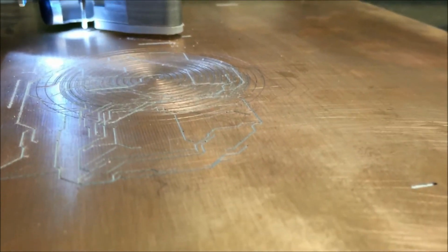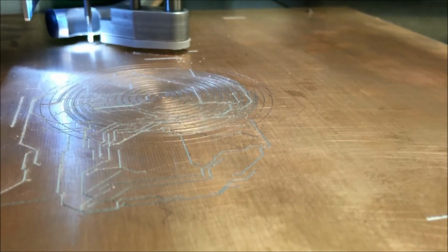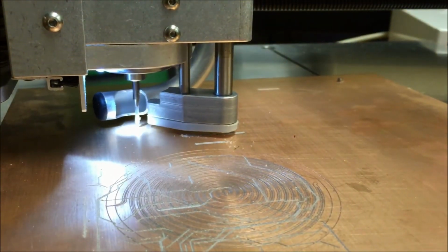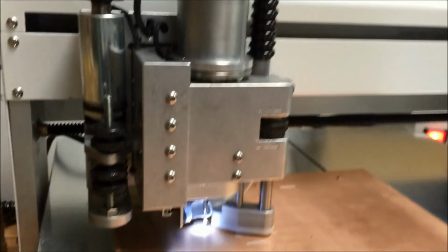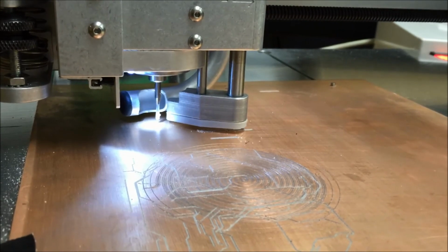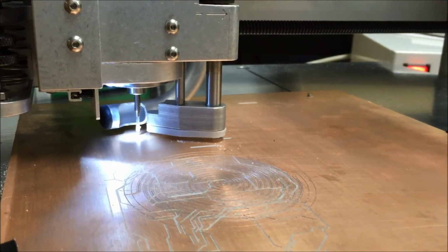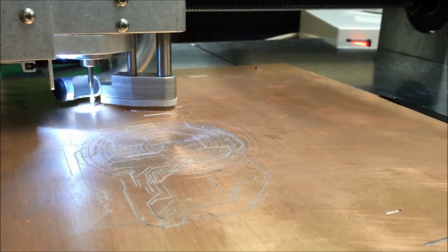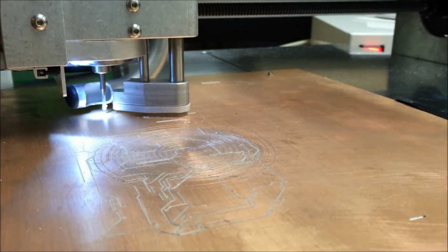Is this a tool with a V-shaped head, where the width of the cut depends on the depth of the cut? Yes. You can see it's V-shaped at the very bottom of it, but the depth of this cut, I'm fairly sure, goes just barely before the total width is reached. Mm-hmm. And again, I did a few of them earlier with different cut depths, and you could just kind of tell what's right because it fills itself in and it doesn't cut much deeper than the actual copper. But I'll find that visual somewhere that tells you what it's actually supposed to look like.